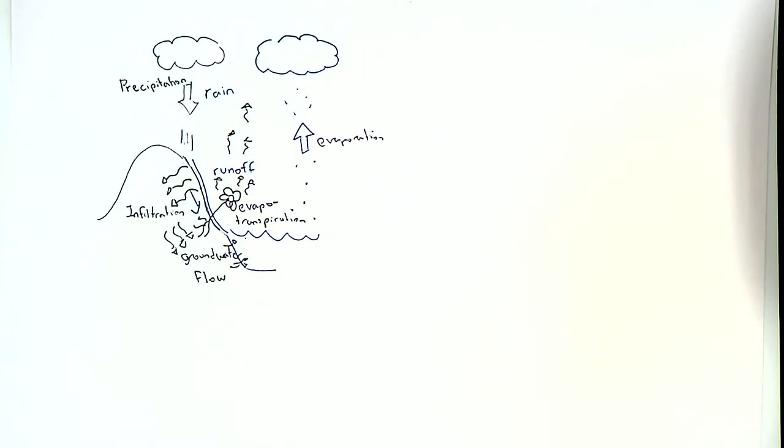Typically, water in water bodies just evaporates, but even within water bodies, water can also infiltrate. However, large water bodies such as lakes are typically saturated, which means that their ground has already infiltrated as much water as it can. So normally for water bodies, evaporation is really the only form of loss of water because the ground should already be saturated if they're large water bodies. Good. There's still other forms of water processes going on, but I think those are the most common ones.